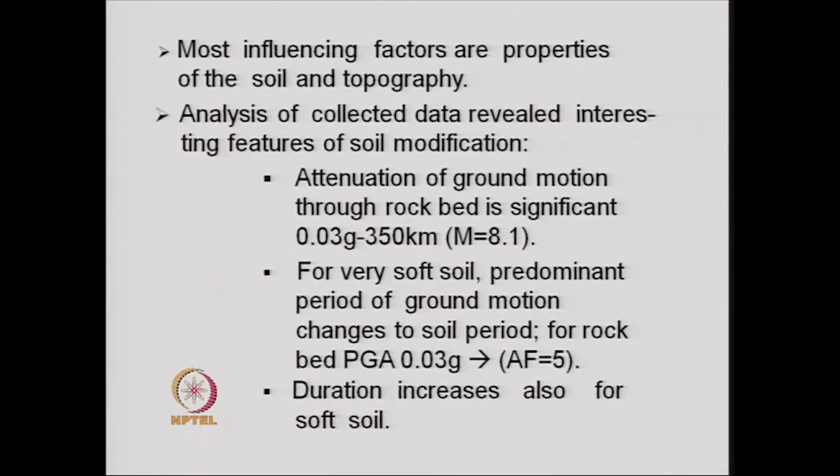The second thing that was observed was for very soft soil, predominant period of ground motion changes to soil period, and there is a large amplification of the ground motion. For a rock bed peak ground acceleration of 0.03 g, the amplification of the amplitude of ground motion was seen to be of the order of 5.